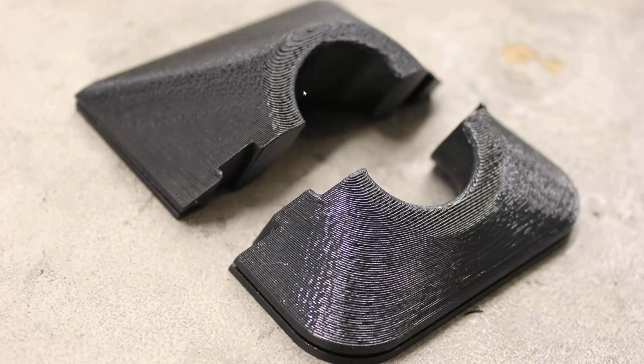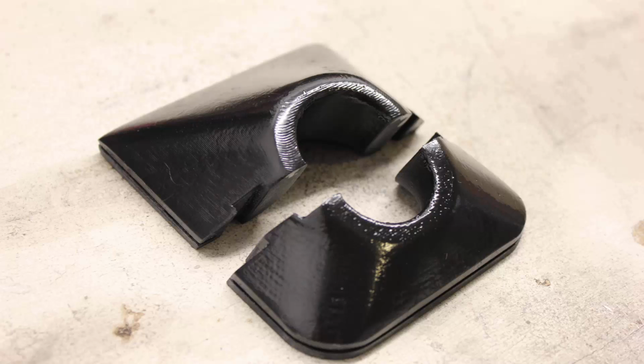So I actually just brushed on the acetone using a paintbrush. If you do this, go buy an acid brush. Don't use a paintbrush, because it killed my paintbrush. I ended up with some hairs in my finished part here. But this is what it ended up looking like. So I spent probably 20 minutes, maybe 25 minutes, painting on the acetone very liberally. A lot of it evaporates quite soon, but if you can build it up on the part, it tends to kind of micro melt it, gives it a little thin skin.